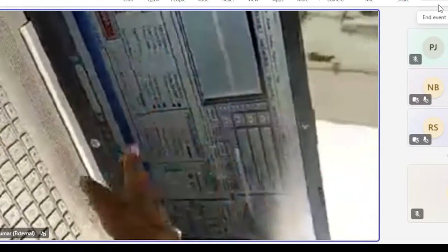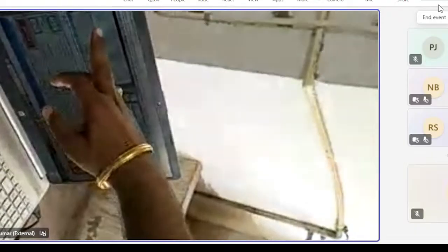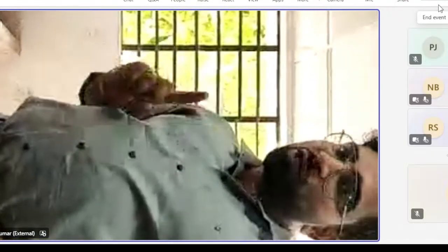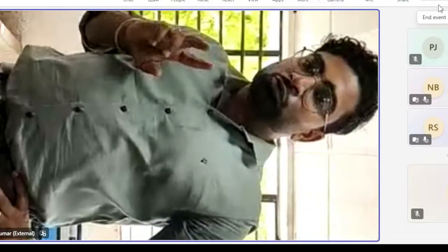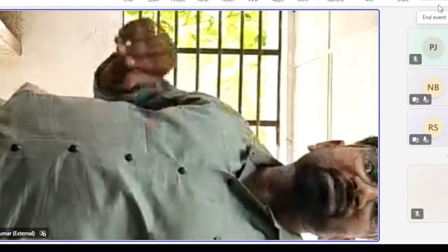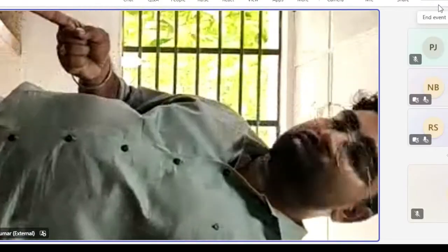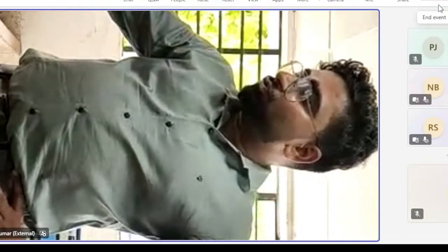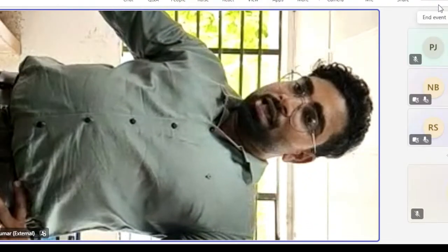Here I have already told you what every code is showing. It is showing M3. Again, I am repeating, M3 is for the torch. We have used one torch. If we use both torches, then the program will start with M3 and M7. And here there is only one torch, so that is why it is M3 only.